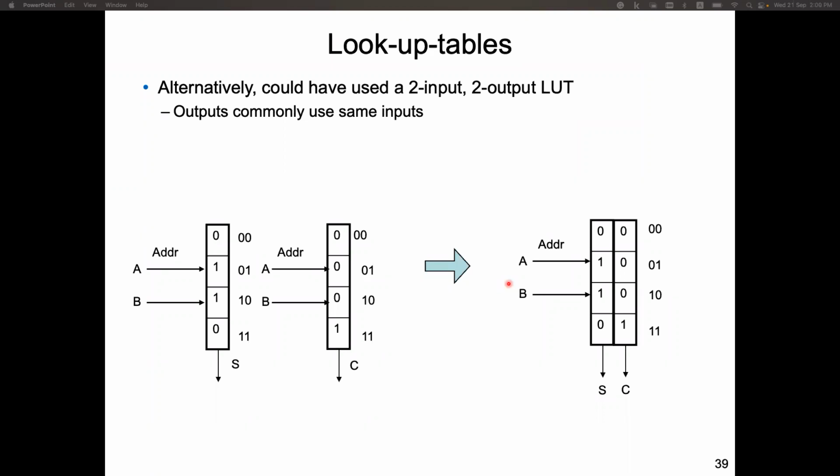So any questions with this lookup table concept? Well, it's simple but very important. It's the fundamental of FPGA. It uses a lookup table to implement an arbitrary logic function. The idea is simple, but FPGA just relies on this idea. And as I said, it uses memories to store the desired outputs. This memory can be rewritten, so we can reprogram the FPGA easily.